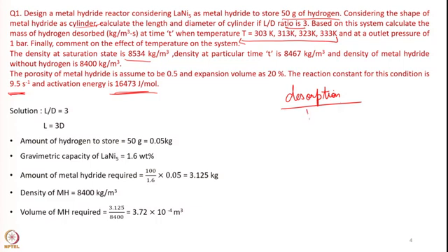This desorption case is generally used for refrigeration, in which when the hydrogen is desorbed, the temperature of the metal hydride reactor decreases, and this provides us the cooling effect.